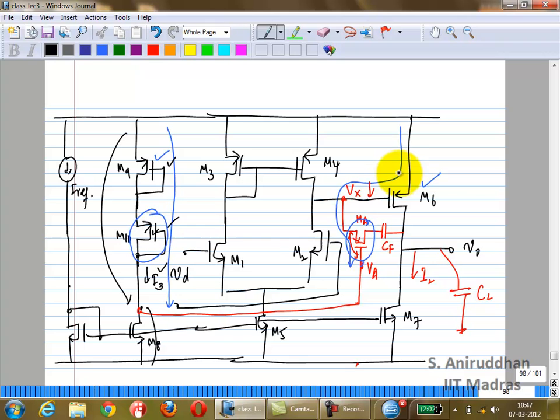What decides whether a transistor is in triode or not? The bias condition, right? After that you apply the small signal, and yeah, you could have a signal current flowing through it. There's no problem with that. But the signal current flowing through it will depend on the resistance, which depends on the bias condition. Right? Yes. Okay, so the resistance, yes, that's right.